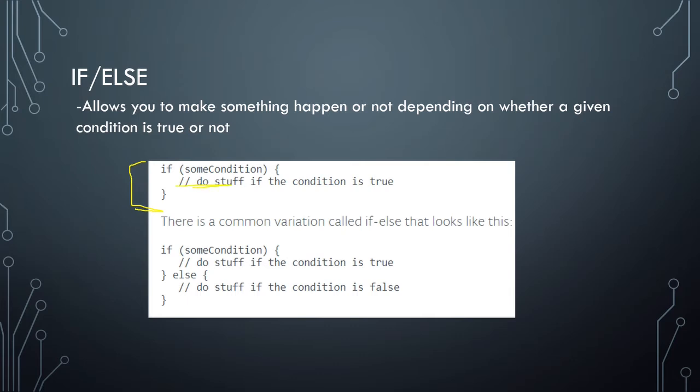We can also do an if-else command. Similar to the if command, if something happens, then do this, or else do this. So it gives an alternative. So it's saying if the button isn't being pushed, then this should be the state. So if we fill in these blanks and say if the push button is low, that would mean it's being pushed.